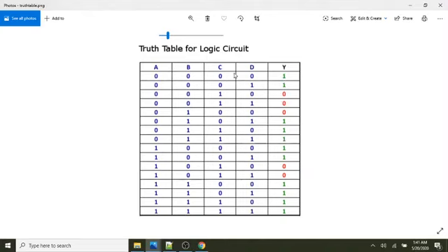Okay, so here, this is it. We've got 4 inputs, we got 16 rows, and these are our outputs, my Y output. So it's either got to be a 1 or a 0. Now, from the truth table, you could write out by hand either the sum of products or product of sums expressions directly from the truth table, but that would be pretty tedious and a lot of logic there. So it's really better to use a Karnaugh map to simplify things.